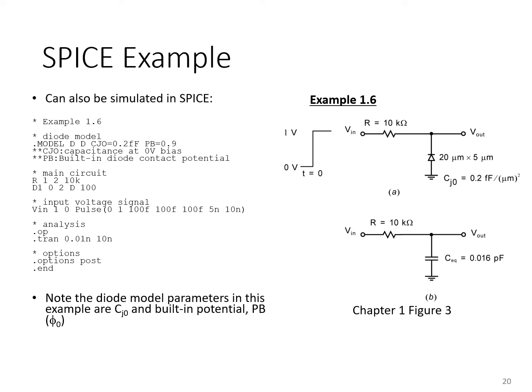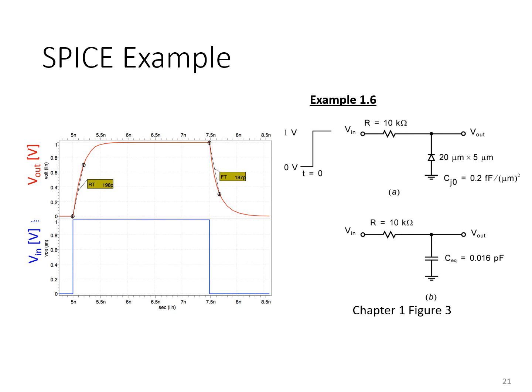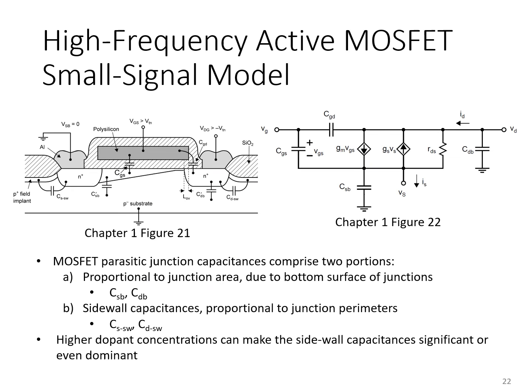And you can try out this analysis in SPICE, and you'll see that the result obtained using that approximate method is more accurate than a simple small signal approximation by comparing with transient simulation. And this is an example taken from the book. There's the results of the simulation. They can be compared with the calculations in the example above.